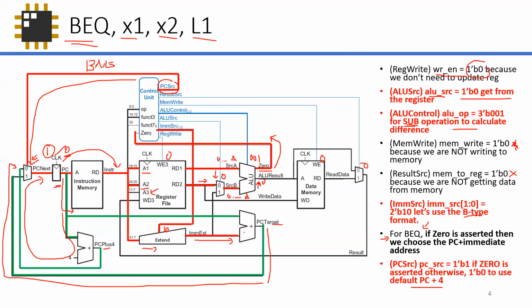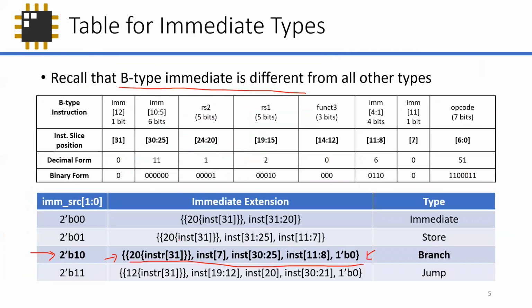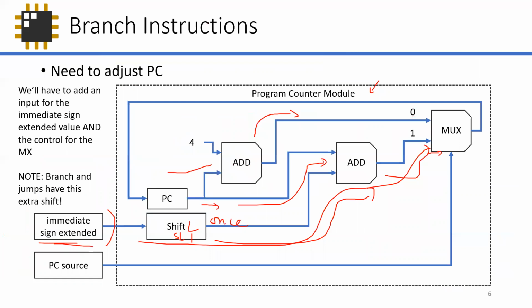So if I go back to our single cycle, we have this extra shift here. You have this shift left one. So you have to add it there before you add it to the program counter. And then you're gonna put it here. But according to some books, they already put it in here the moment you try to select that. So for now, we'll stick to what RISC-V tells us to do, because that's the standard that they're asking.